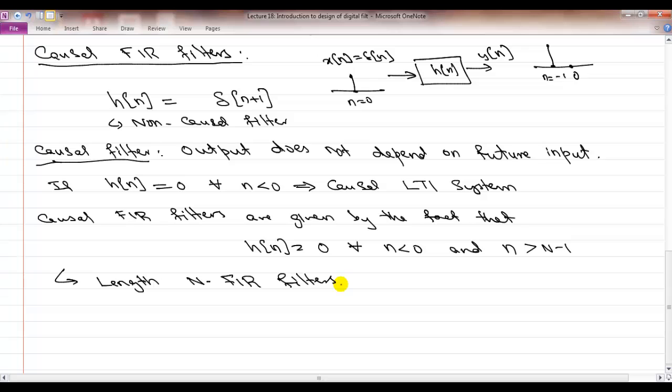Whenever we are talking about design of digital filters using FIR filters, we'll stick with causal FIR filters. If I just say I'm talking about a length 128 filter, the automatic assumption is that it's a filter that goes from h[n] for n equal to 0 to n equal to 127. Those are the specific definitions of FIR filters, causal FIR filters. Let's now go back to the question of why an FIR filter, and specifically a causal FIR filter, is implementable.